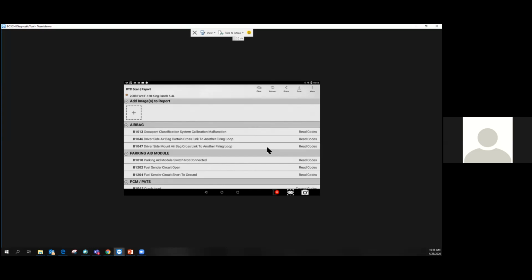You're going to have static fault codes that will clear out no problem. But as soon as you take it for a test drive, that system gets activated, that component gets turned on, goes through a drive cycle. Those fault codes could come back. But I always recommend a post-scan when the vehicle repairs are done before your test drive, and another post-scan as soon as the test drive is done to make sure that after the drive cycle was performed, nothing recurred, and to let you know you need to go back in there further.